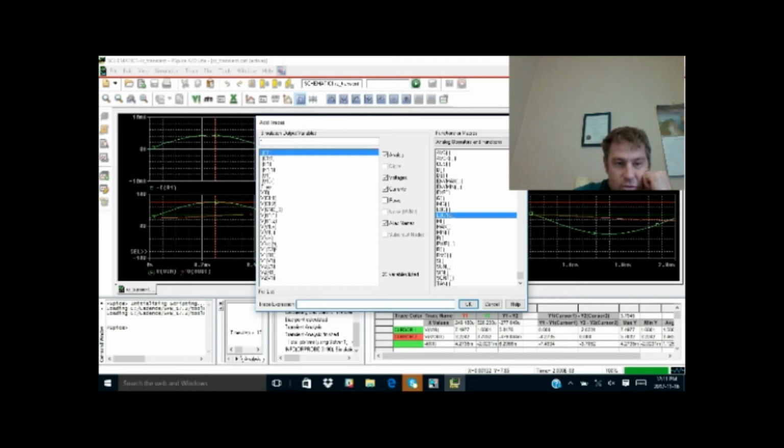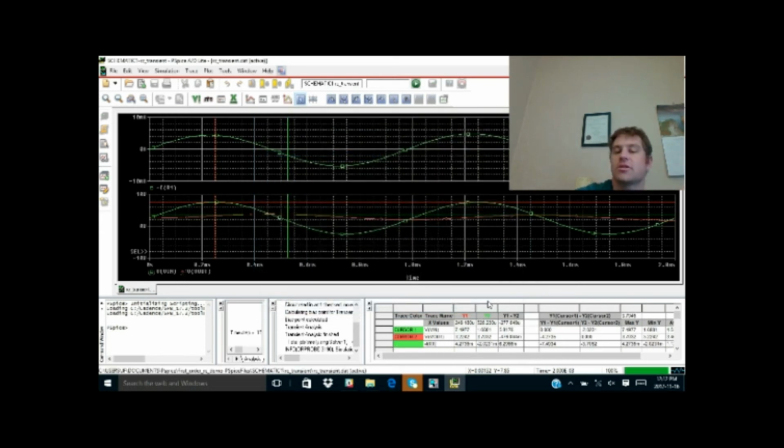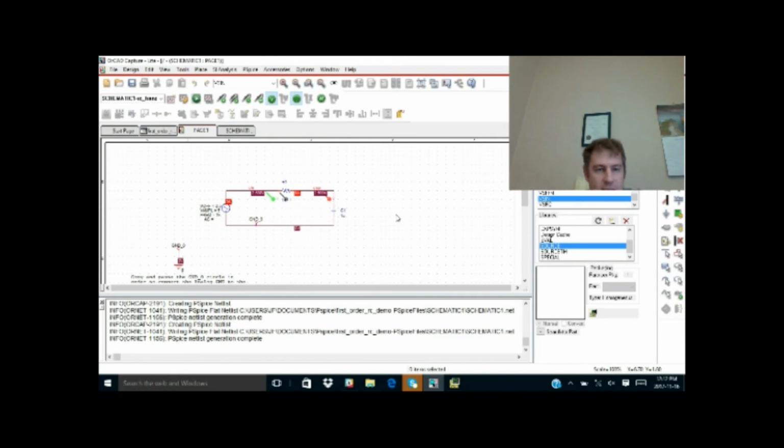For example, we're going to do this in the frequency domain, because right now it's not applicable, but there you go. This is the output of your simulation result for this circuit. One more thing we can look at is the bias point. My voltage operating point is shown here, and the current shown here is the DC current flowing through my circuit. This is expected, right? There's no DC current flowing through that circuit because the capacitor is an open circuit.